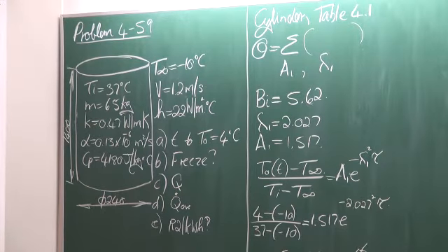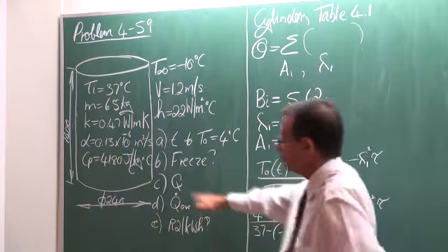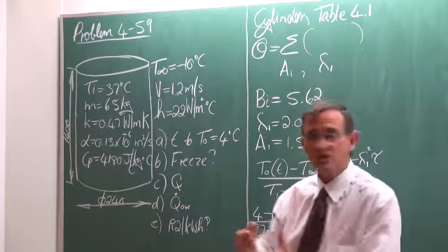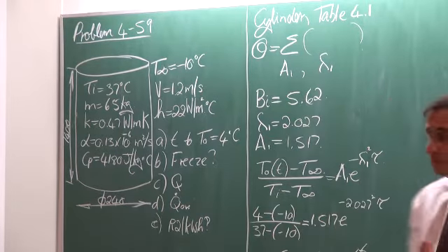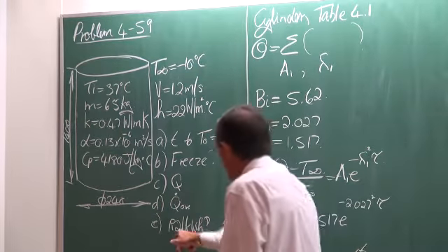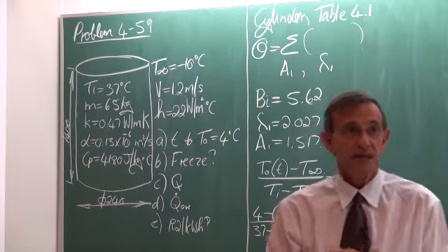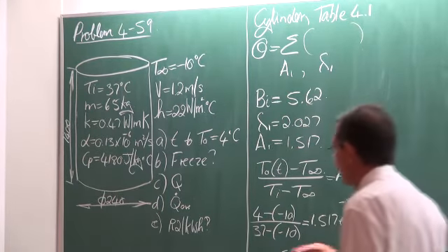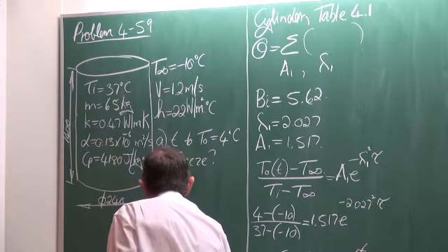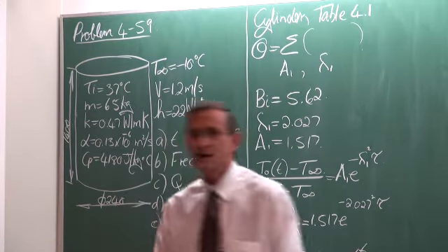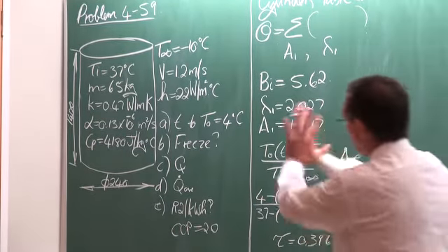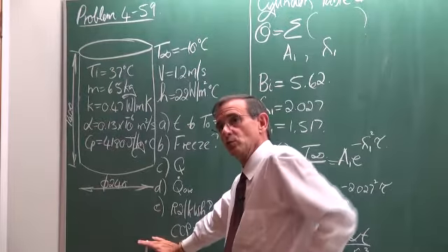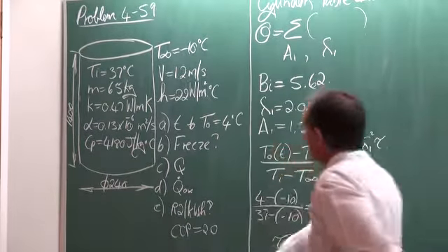And then I've added a few more questions to this problem, and that is to determine the amount of heat transfer, which is in joules, then the average heat transfer rate, how many watts over the period, and then how much it will cost if the electricity tariff is 2 Rand per kilowatt hour. I think I've set a COP value of the vapor compression refrigeration system of typically about 2. So that was the problem, and in the previous lecture we've already started with it. We've done it in much more detail.